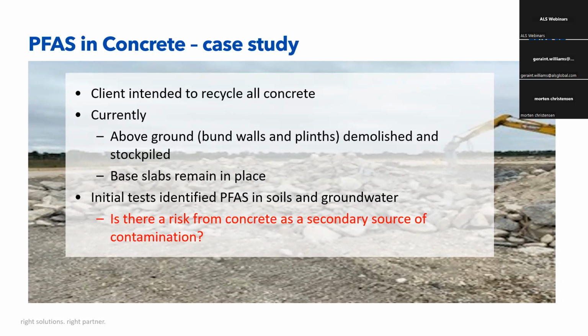We were involved in a project where we were looking at PFAS in concrete. Concrete can be very porous, which allows PFAS to diffuse, partition and self-assemble on surfaces, especially in fire training areas where AFFF has been used over years or decades. And we're seeing PFAS leach from concrete over time, and that acts as a secondary source of contamination. So you could spend many millions or many hundreds of thousands of dollars remediating a site where you're dealing with the soils and the groundwater.